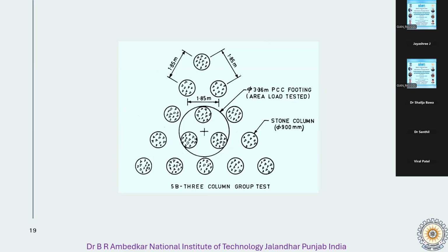So here again, the initial and final soil conditions at the trial site should be investigated by drilling at least one borehole, and one static cone test, or the pressure meter test, or the dynamic cone test should be done to assess the properties of the soil.